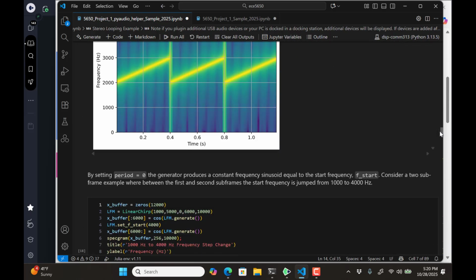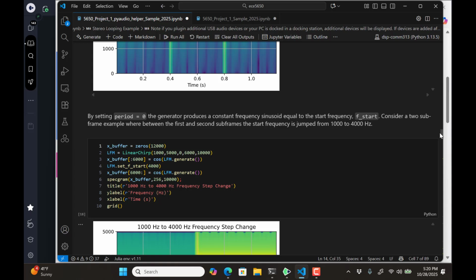but since we were talking about spectrum, let's just stop there for a second, because this is pretty much identical to what you saw in 2610 when you collect some outputs from a buffer and then you want to get a spectrum, which is shown down here. You put the buffer into here, the number of points in the FFT, and that's going to be the vertical resolution for the frequency. And then the sampling rate is the last variable, I think.